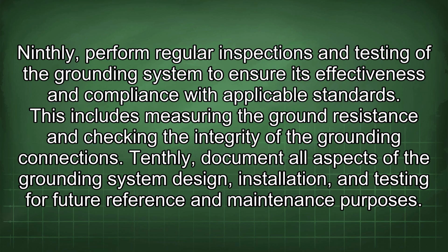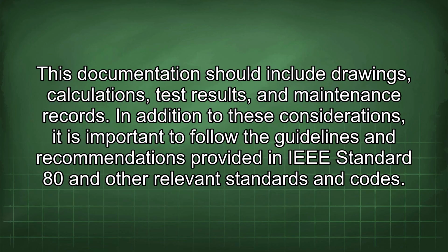Ninthly, perform regular inspections and testing of the grounding system to ensure its effectiveness and compliance with applicable standards. This includes measuring the ground resistance and checking the integrity of the grounding connections. Tenthly, document all aspects of the grounding system design, installation, and testing for future reference and maintenance purposes. This documentation should include drawings, calculations, test results, and maintenance records.